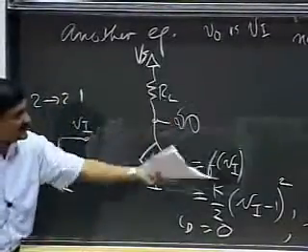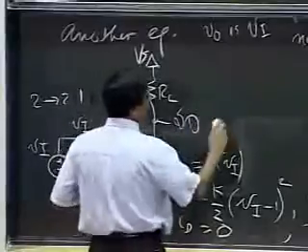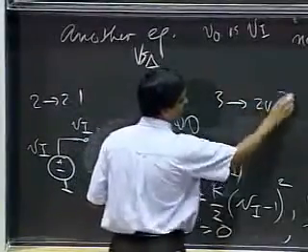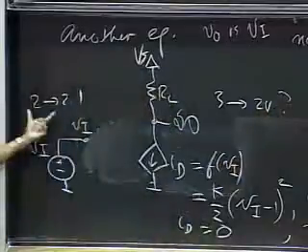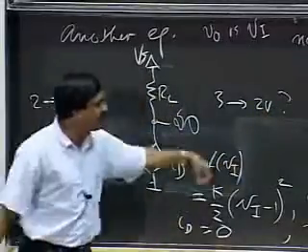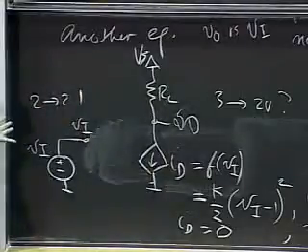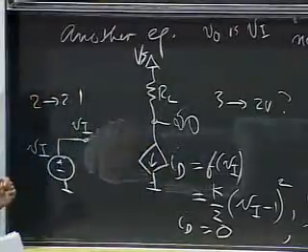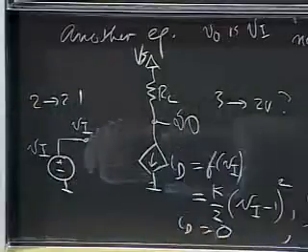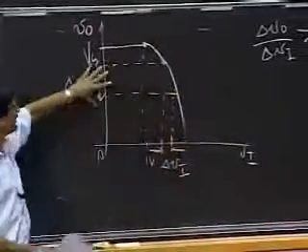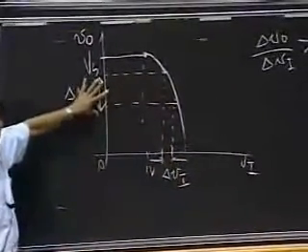But abstractly out there, I might have an output that goes from 3 to, let's say, 2 volts perhaps. So for a 0.1 change here, I'm going to get a bigger drop here, say from 3 volts to 2 volts, giving me an amplification in this little circuit. We'll see this again and again, and you'll really understand it. So I have a small change in the input, and a correspondingly larger change in the output.